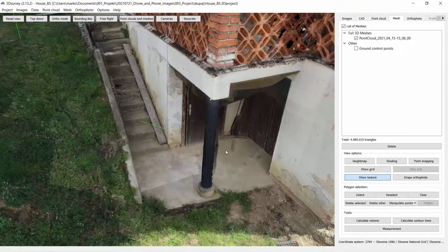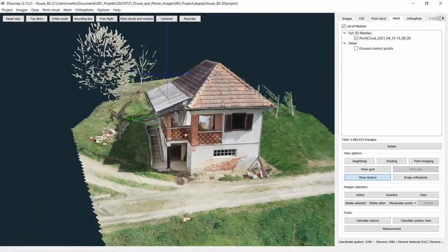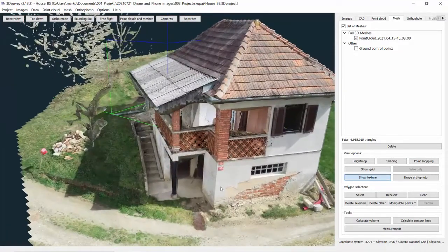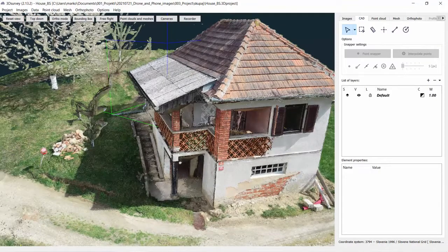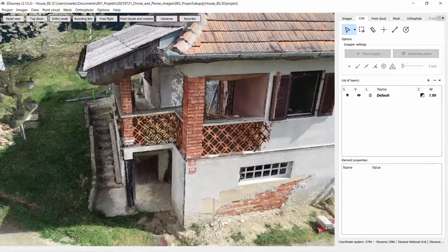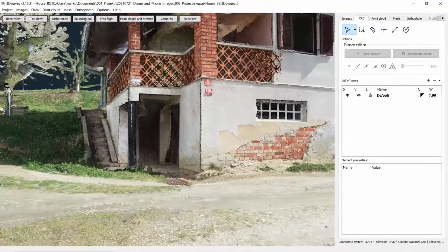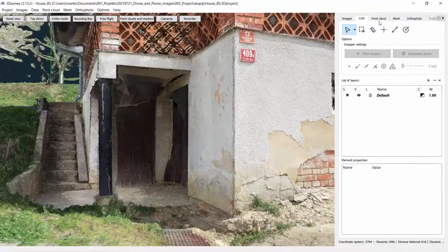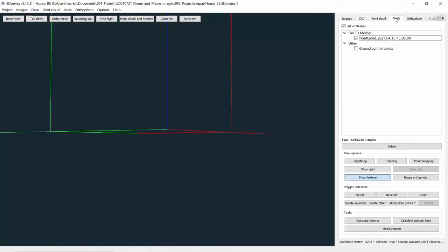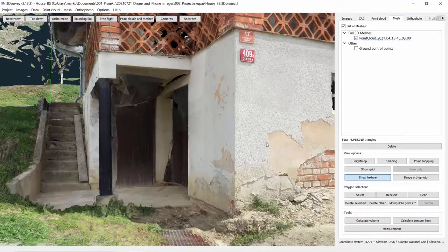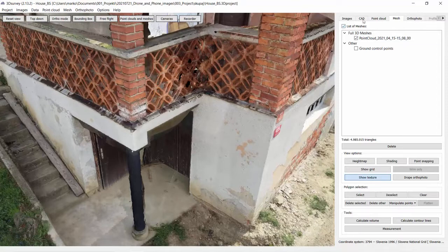Let's try and draw now my main important things for this building. So I need a footprint. Let's go to the CAD tab. What I can do here, currently I see point cloud and mesh, which are available for this model right now. Because I'm comfortable with the mesh, I will just select my mesh and I'm going to draw based on mesh because it's super detailed.